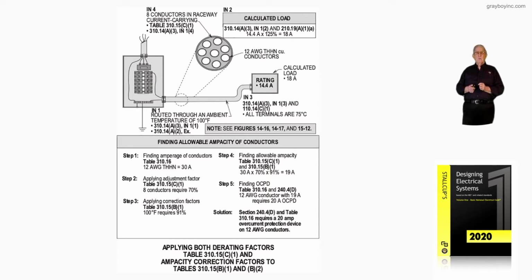Now, to review these methods, the overcurrent protection device and the conductors have to have enough ampacity to supply that equipment as a branch circuit. Some of you remember in the 2017 NEC, this same rule appeared in the 215.2(A)(1) section for feeders, but they've added it to the branch circuits because it's applicable here. And notice what's taken place.